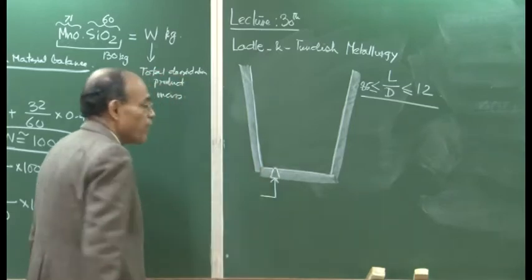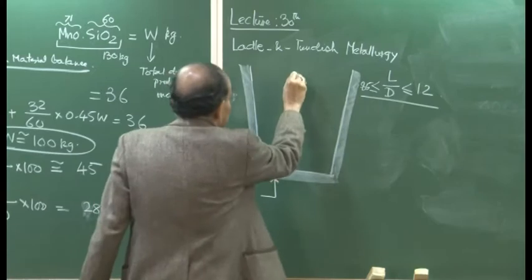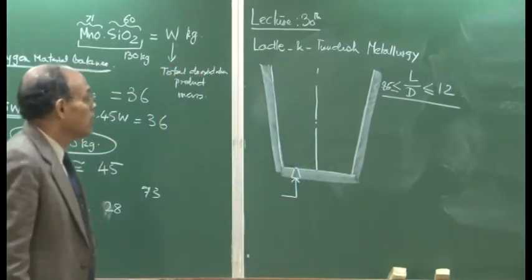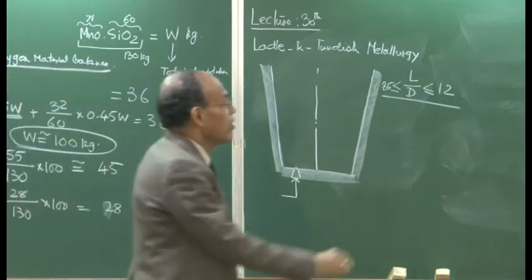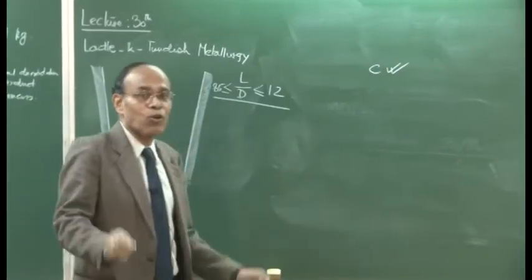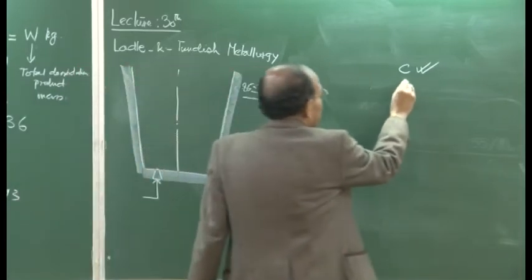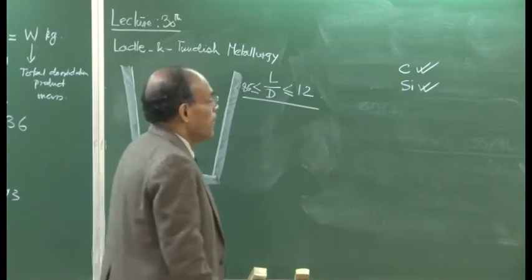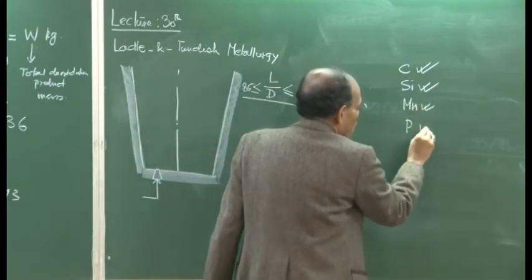A refractory artifact through which gas is going to be blown, and that gas is an inert gas. Now, when you have tapped molten metal into the ladle, we must understand that we have carbon absolutely as per the desired level specified by the customer, silicon no problem, manganese, phosphorus no problem.